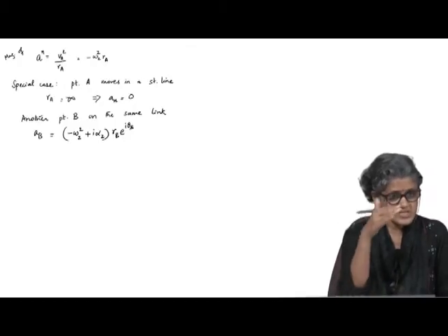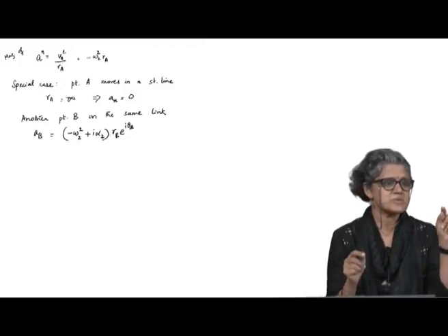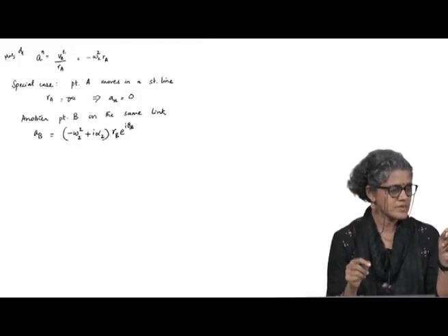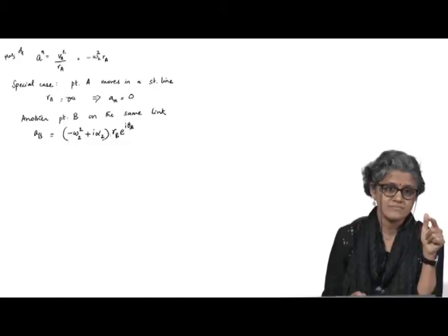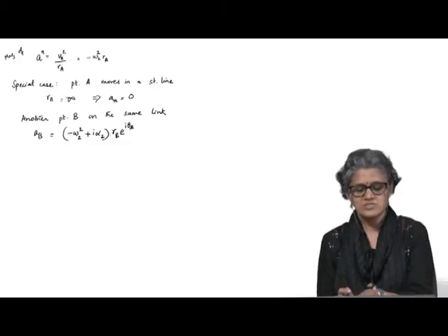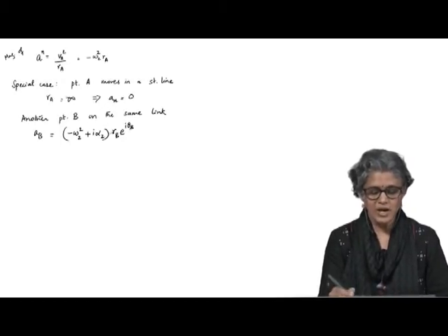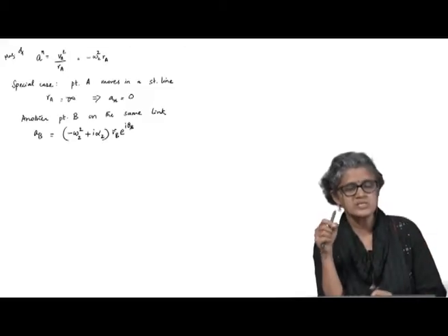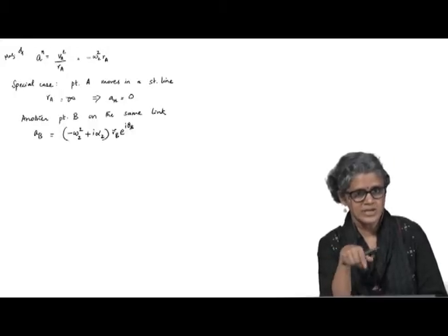So, the direction of its tangential component, even though the factor is the same, r_B is changing, so there is an acceleration difference between the 2 points, even if the link is rotating at a constant angular velocity. Even if alpha_2 is 0, omega_2 and alpha_2 are for the link, but specific points will have different accelerations because that will depend on where they are located on the link.